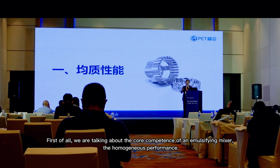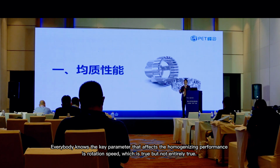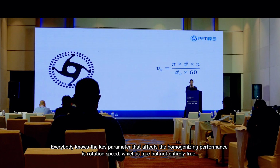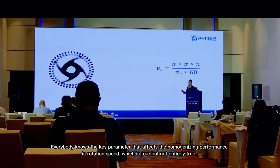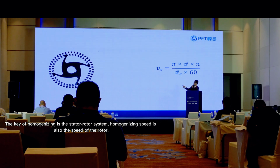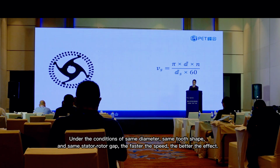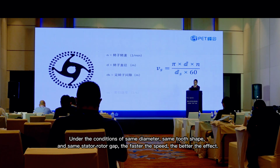First of all, we are talking about the core competence of an emulsifying mixer, the homogenizing performance. The quality of homogenizing performance directly affects whether the product can be made and whether the product is stable. Everybody knows the key parameter that affects the homogenizing performance is rotation speed, which is true but not entirely true. The key of homogenizing is the stator-rotor system. Homogenizing speed is also the speed of the rotor. Under the conditions of same diameter, same tooth shape, and same stator-rotor gap, the faster the speed, the better the effect.